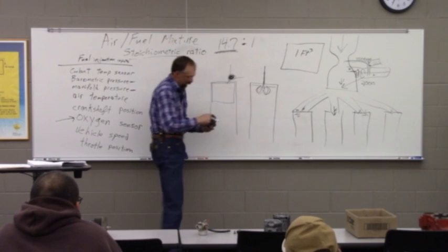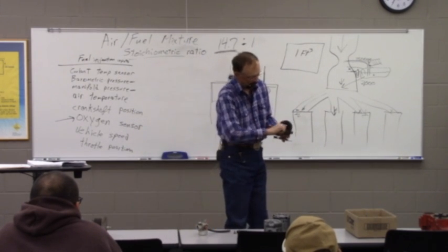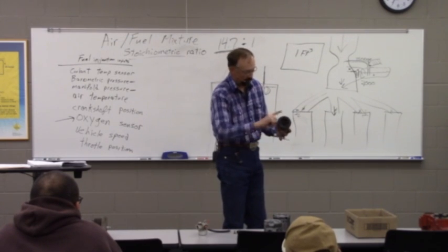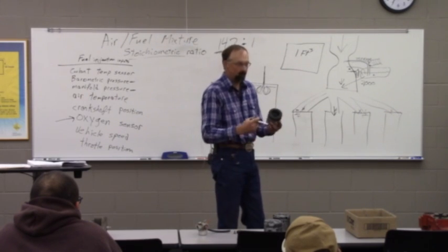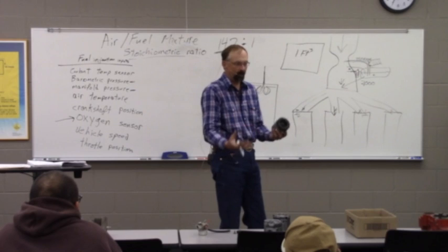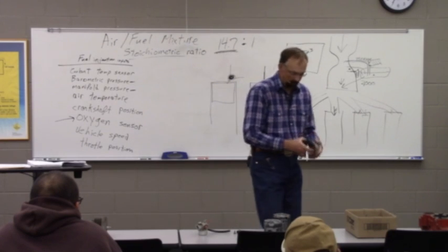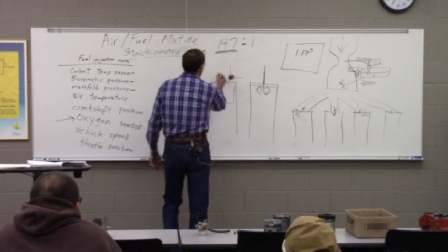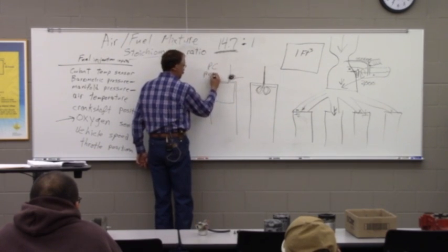So it goes down near this raised point in the middle, and it comes back up around the edges, and all the way around you've got this swirling action that gets all the fuel mixing with the oxygen and vaporizing from liquid into vapor and starting the combustion process. And so these are called PC, or pre-combustion chamber engines.